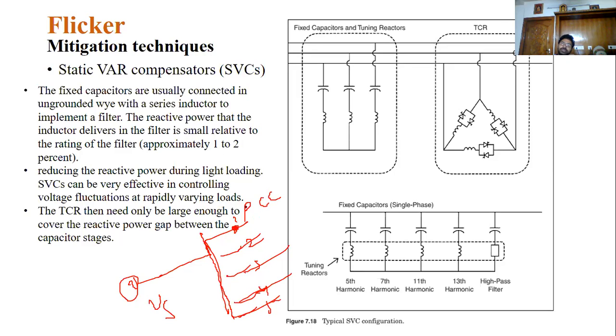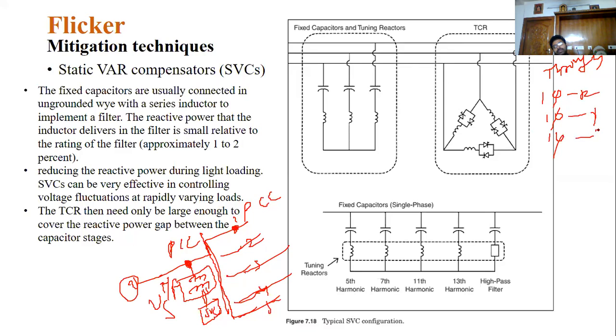So at this PCC, how are these devices connected? Through a transformer. Suppose this is the PCC. The device is connected using a transformer; you are not injecting directly. The transformer may be a three-phase linear transformer, with constant primary and secondary, or three single-phase transformers. The most advantageous case is three single-phase transformers, one single phase each for the three phases.